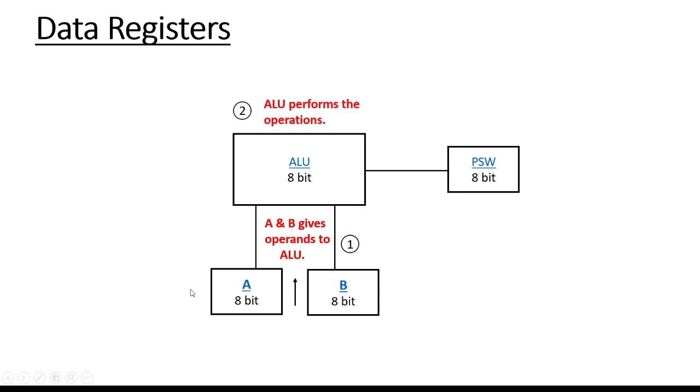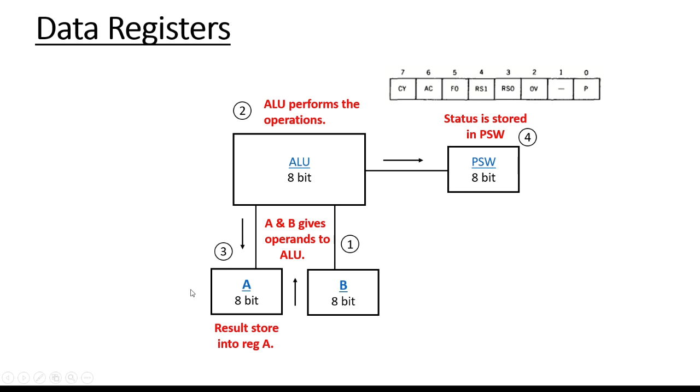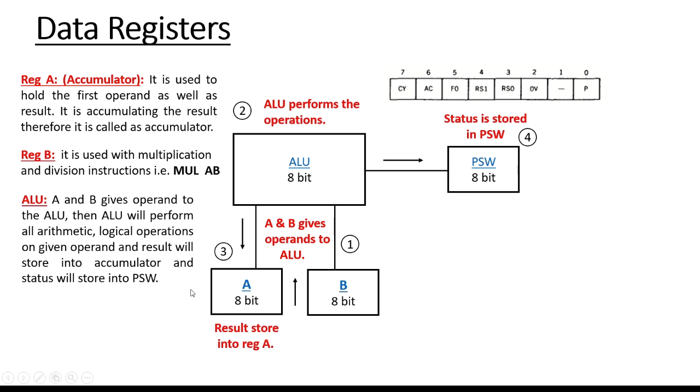The ALU performs the operation, which could be arithmetic and logical operations. After performing the operation, the result is stored into A, and the status of the operation is stored in the PSW. The PSW is nothing but the 8-bit flag register.